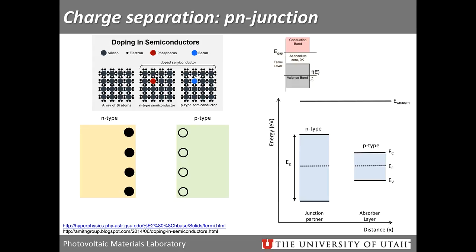Okay. So yes. An intrinsic semiconductor, when the valence band is completely full, so you have no excitation, and the conduction band is completely empty, your Fermi level is at mid-band gap. So that's technically where your occupation probability is 50%, assuming Fermi statistics. Does that make sense to everyone?